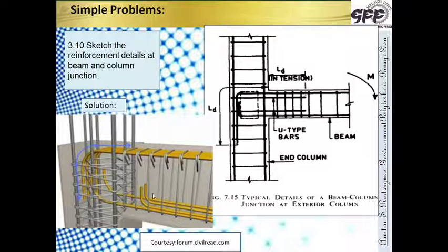Over here, to see it practically, the top reinforcement goes like this, the bottom reinforcement goes like this. So from the face of the column, observe the distance of the bent bar, not the bent up, sorry, the distance from here of the whole thing, this is taken as LD. So whatever anchorage is required, it is from here to here. That is the length which is required to be provided.